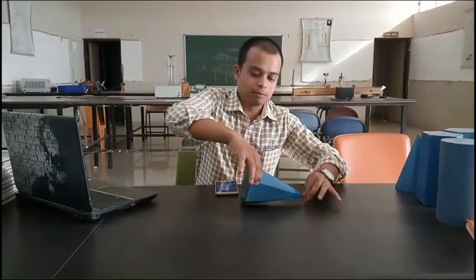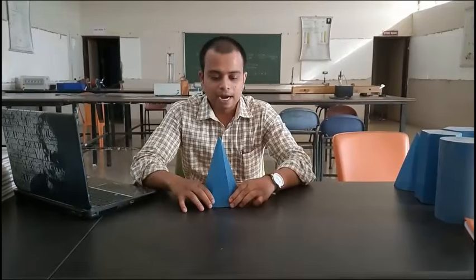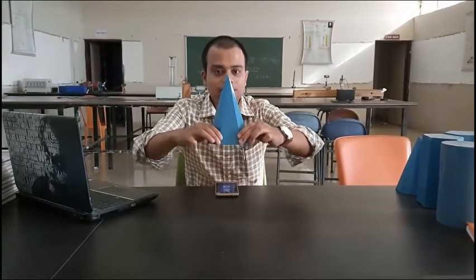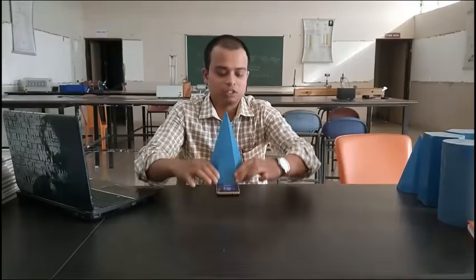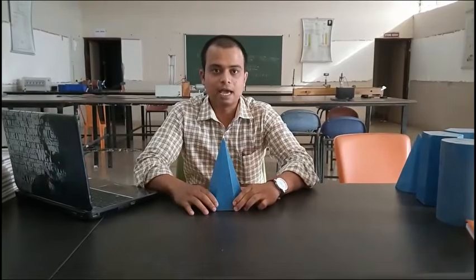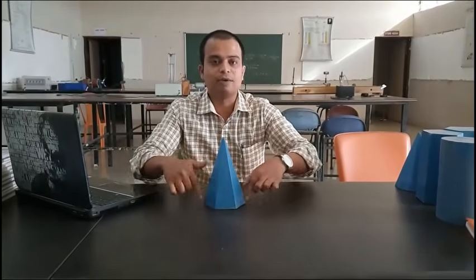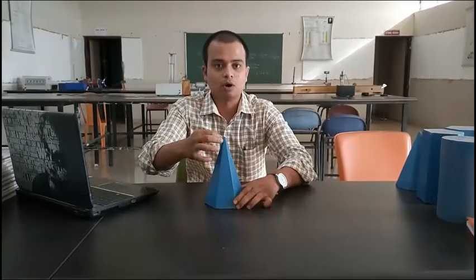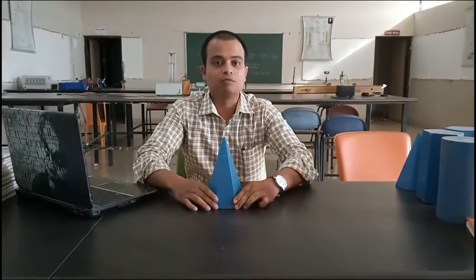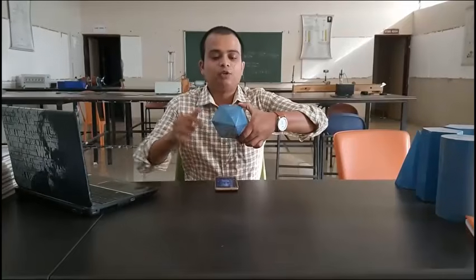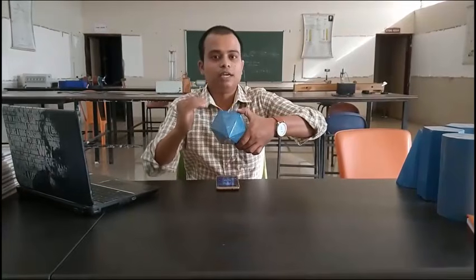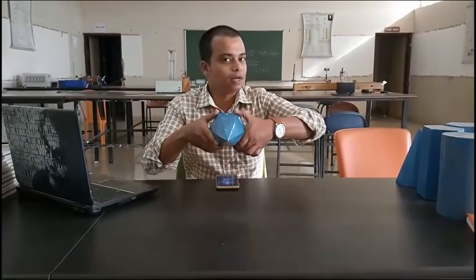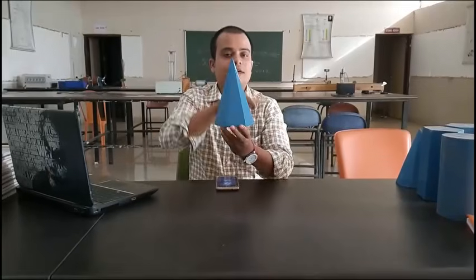This is going to be step number 2, step number 1, and you can clearly see that this particular hexagonal pyramid is resting with its base on the horizontal plane, and hence the true shape of the base is going to be seen from the top. So this is exactly what you're going to observe from the top. You have to begin by drawing this kind of a hexagon below the XY line. This is step number 1. Then accordingly, this triangle can be made in the front view.